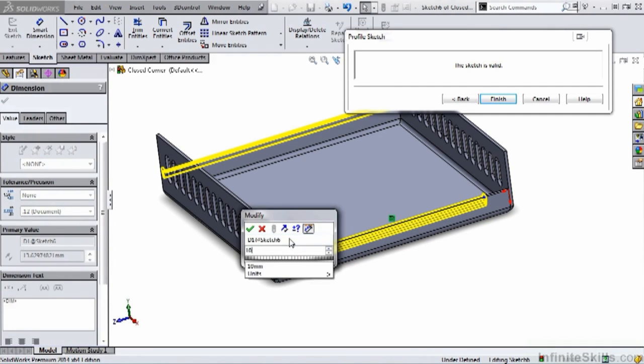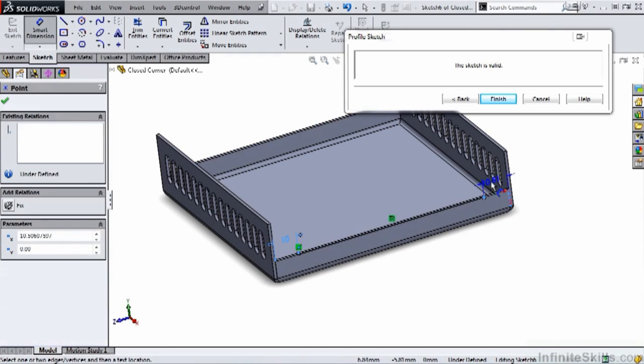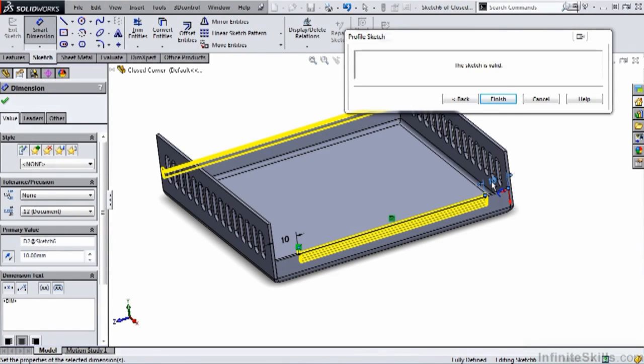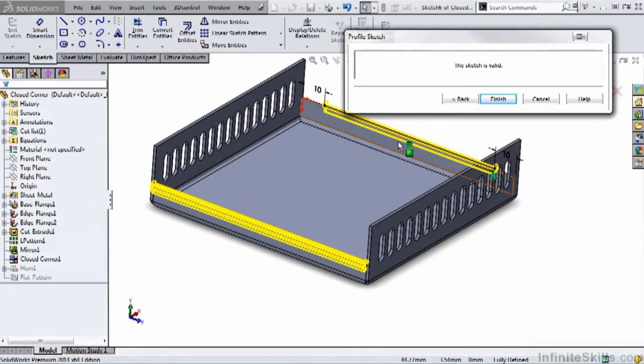We'll set this one to 10, and we'll do the same with this one, 10. Now if I try to do the same to the opposite side, you'll notice, unlike the first hem, on this side where we have the black line with the 2 black dots, we do not have that black line with the 2 black dots. So we cannot shorten this hem. So if we wanted symmetrical hems, we should not have selected multiple edges. I do want the hems to be symmetrical.